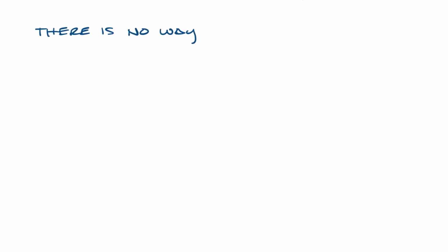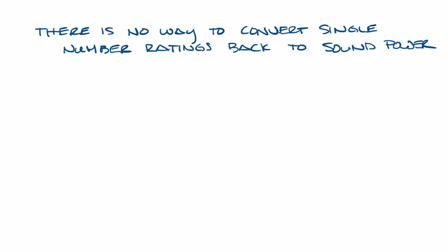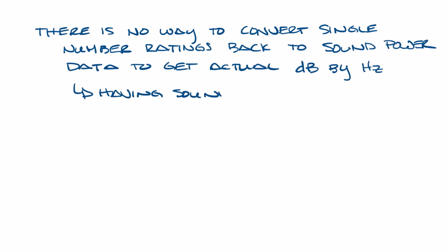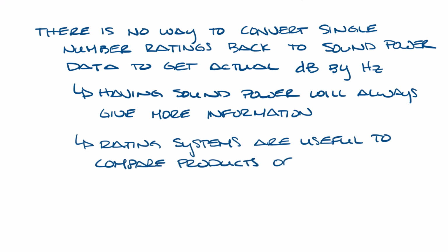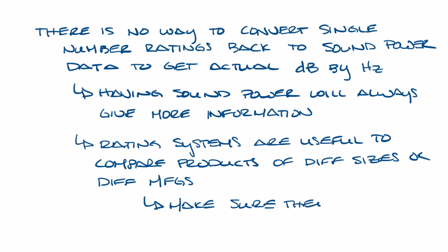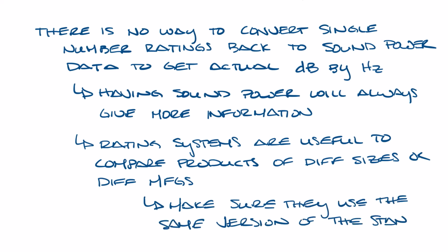There's no way to convert any of these single number rating systems back into the original sound power to get the actual decibel by frequency information. So having the actual sound power will always give you more information, but the rating systems are useful to compare the same product in different sizes or from different manufacturers. But remember from a couple videos back, this only works if they are using the same version of the test standard to publish their data.